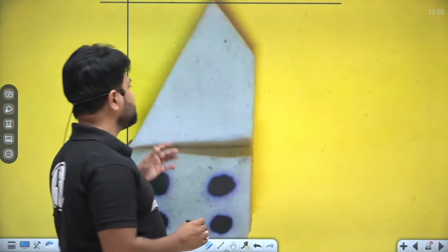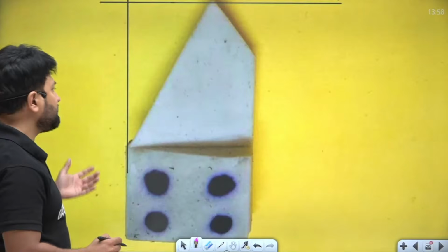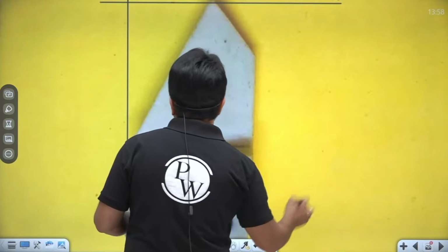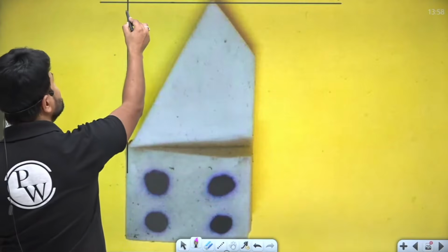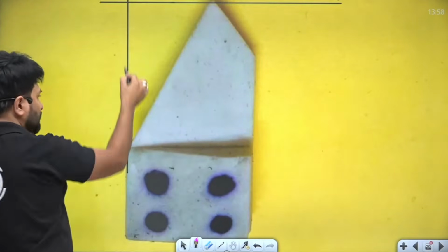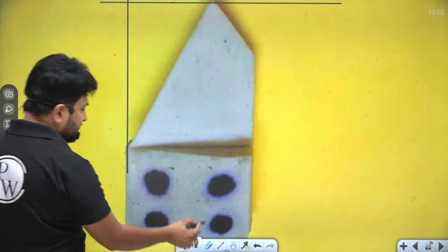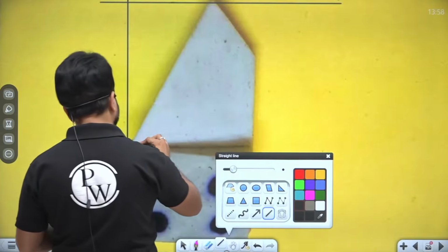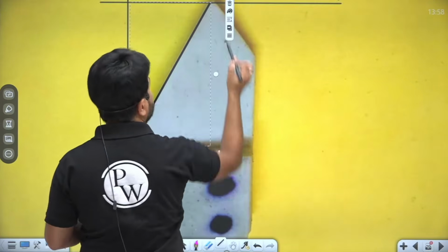My dear, this is the top view of this plane. Basically, it is a plane which is parallel to the base of the tool and along the length of the tool. In this plane, this is the side cutting edge, my dear.